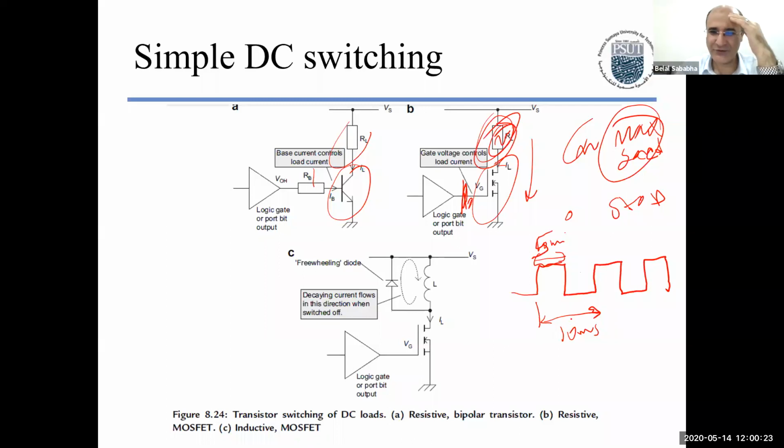So it will be 5 low. Then the motor is on average moving at half speed. If you go 7.5 milliseconds high, 2.5 milliseconds low, then you're moving, for example, 3/4 of the speed, right? So every time you change the amount of being high against the amount you're going to stay low, you will be changing the speed, okay? And we talked about this.